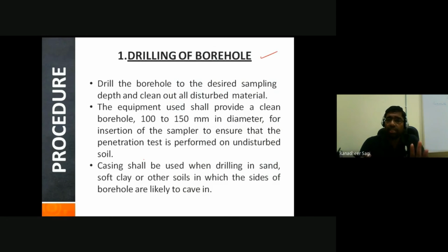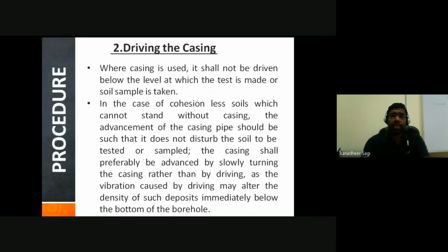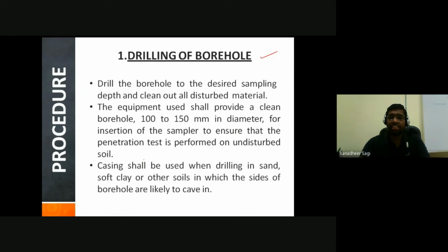So as we have said, this SPT test is more suitable in the case of your cohesionless soil, but however, it doesn't mean that you cannot perform your SPT test for other type of soils. Even for cohesive soil, you can perform the SPT test, or for cohesionless soil also, you can go on to perform your SPT test. Okay. But in case if you are performing the SPT test in sandy soil deposit, you should be using what is called as a casing while making the borehole into the ground.